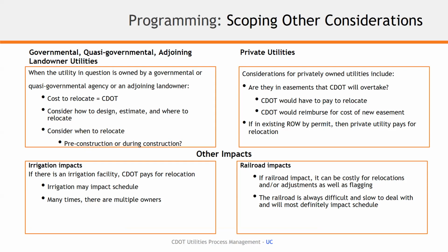These are really good, I think, a good due diligence slide, because it can have such significant impacts on design phase, and its cost and schedule. Are you designing a water line, as well as figuring out how to construct it with your own contractor? Is it going to impact your construction phasing? Is it such a significant number of utilities to be relocated within the site that you actually have to schedule a utility relocation phase prior to road construction? So these steps are important.